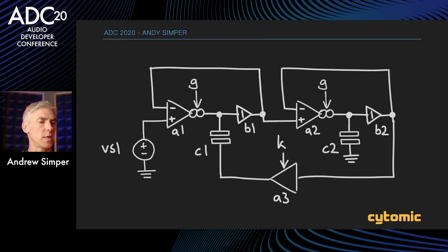Let's get into our second example to show the difference between nodal and state space, and some of the problems that come up when your circuit gets a bit bigger. This is a highly parametric circuit. This is a Sallen-Key filter, the type of filter that's in the MS-20 that I showed at the start. We have our cutoff frequency, which is a gain here. These guys output a current: they take a voltage difference here and output a current to the capacitor. This section is a one-pole low-pass filter, but it has some feedback coming down the bottom leg here instead of just going to ground. So this gives our resonance.